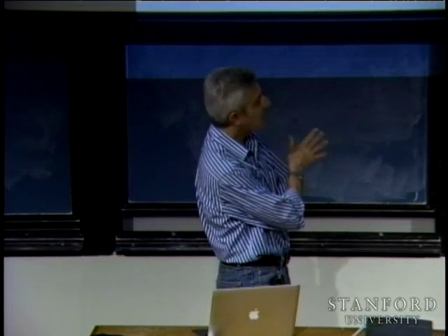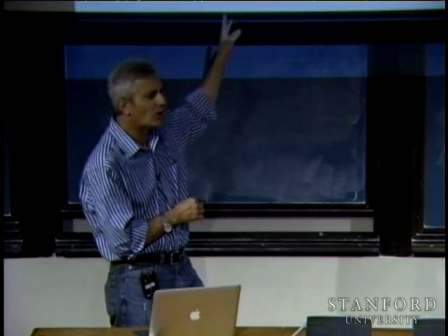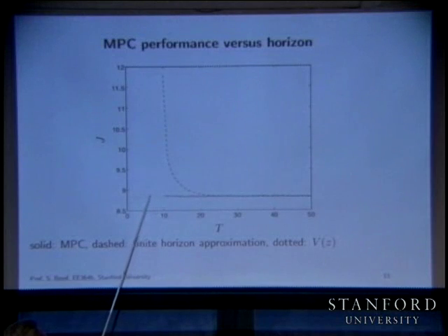The other thing is that when you run this, believe it or not, it'll work perfectly well if you violate feasibility. So if instead of saying x of t plus big T is equal to 0, I put a big charge on capital X of t, like 10 times its absolute value, or 1 norm or something like that, this would work well, or tolerably. Because it would just try its best to get that state to 0. I mean, it wouldn't get great performance, but it wouldn't just stop, right?